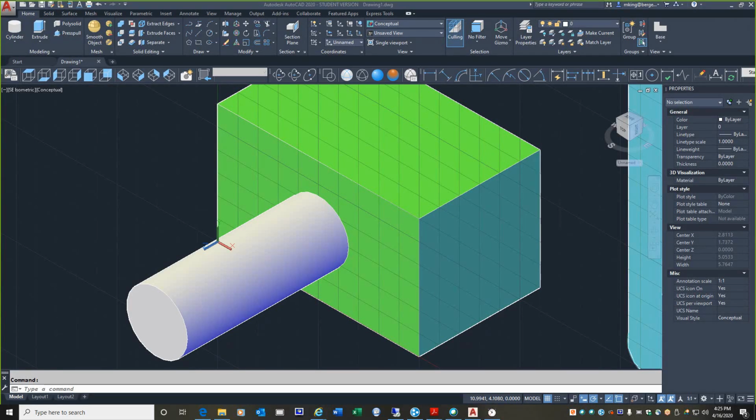All right, so we just finished by creating that cylinder off the left side. I'm going to do another one coming off to the right. So if you didn't get that one, watch carefully and we'll get the second one. What we did is we had to get Z pointing outward from the face that we intend on constructing the cylinder. So now I need Z to be pointing outward from that face.